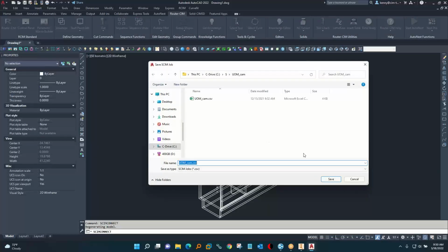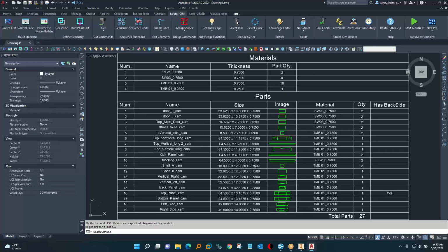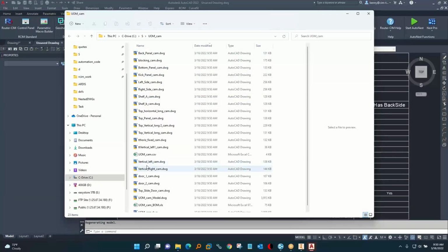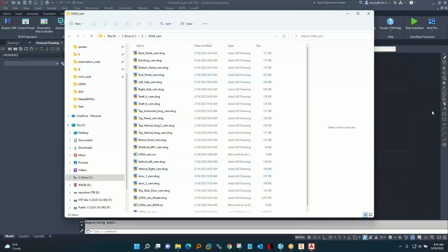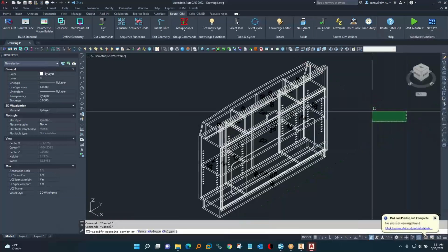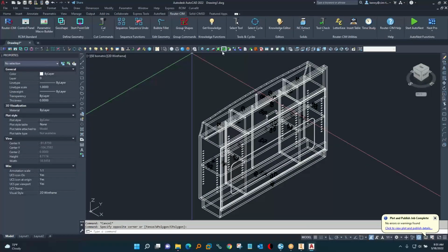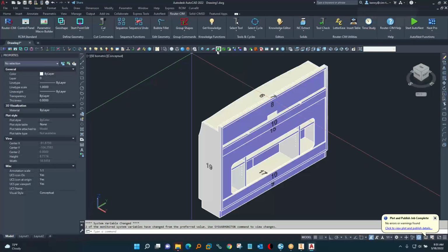And you can have a list of MDF door sizes and it'll process them automatically. So there's all the part names from Inventor, and there's the cut list that's generated. And so you're done here, but you could do the expand and the lay flat if you like.